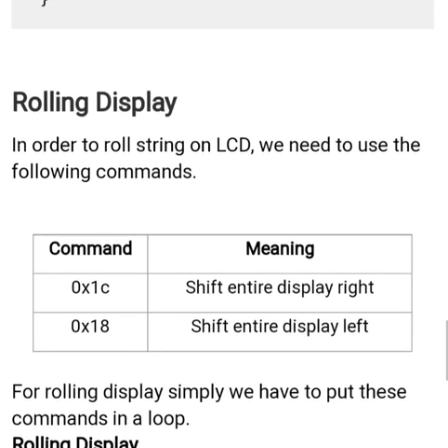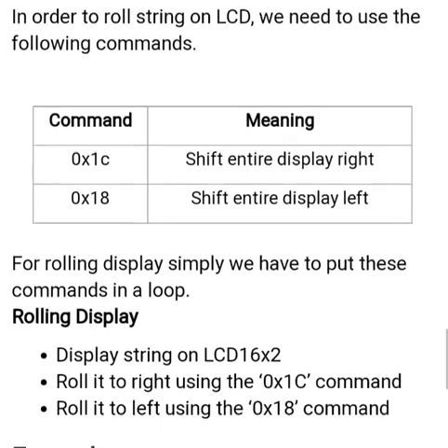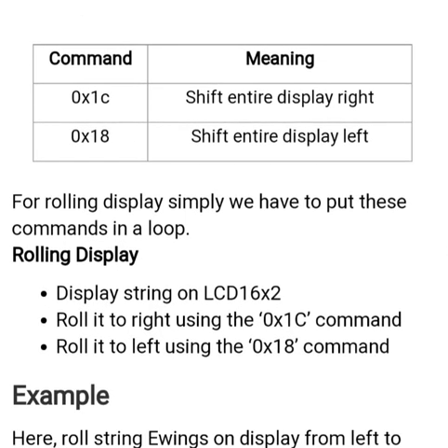Now for rolling display, we need to use these 2 commands, that is 0x1C and 0x18. 0x1C means shift entire display right, and 0x18 means shift entire display to the left.